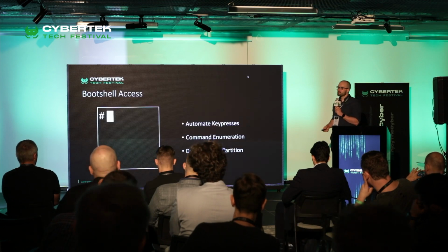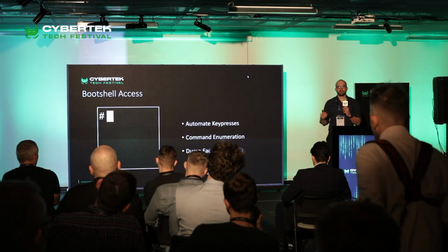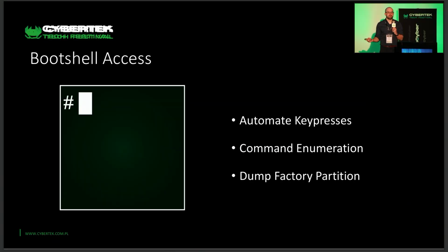So let's get boot shell access next. We want to automate our key presses. Then when we're in, we enumerate the available commands and dump the factory partition.